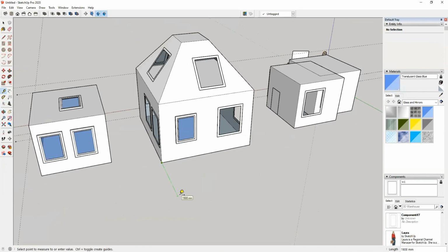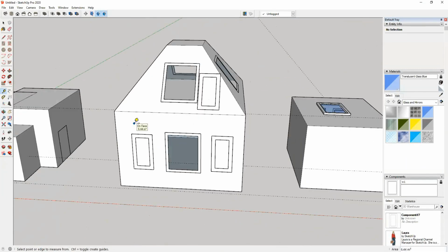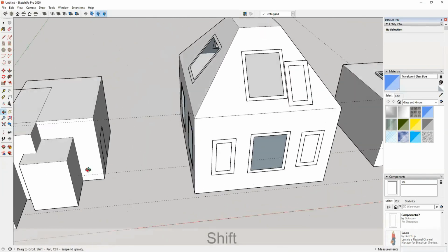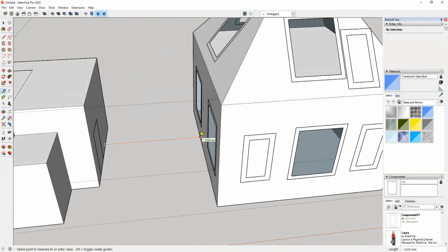And also, in case you don't want to create guides, you just want to take measurements, you can just click on the control key once and then you can just measure the distance from one point to the other and it will not draw a line or a guide. If you don't see the plus icon, then it will not create a guide.